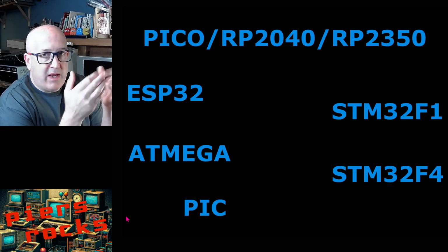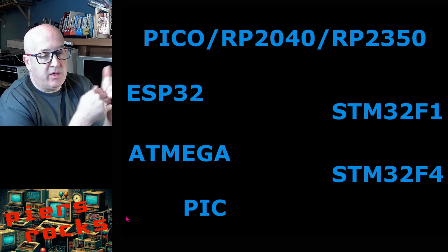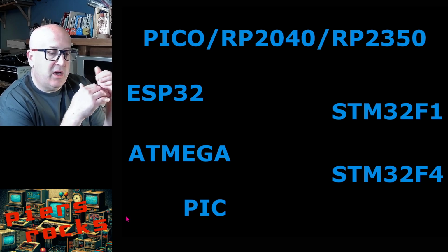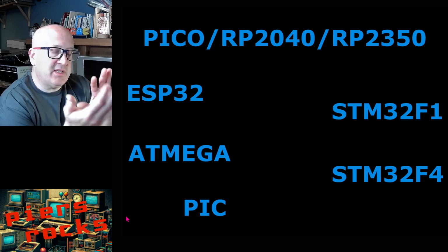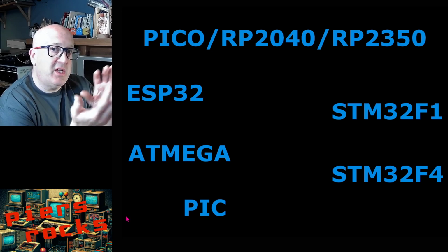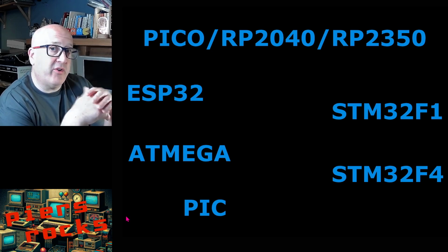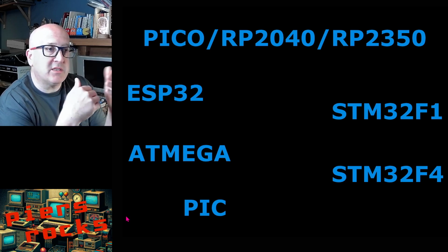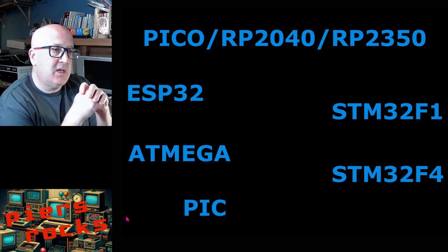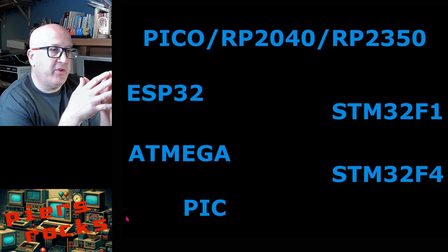Anyway, back to the STM32F1. Relatively low clock speed. It's also an earlier ARM Cortex processor than the STM32F4, and it has much worse instruction prefetching and caching, which influences how fast the processor can actually get the instructions in from flash, and that influences how fast and how deterministically the code will run. And again, some early prototyping suggested that it just wasn't going to be viable on the STM32F1.